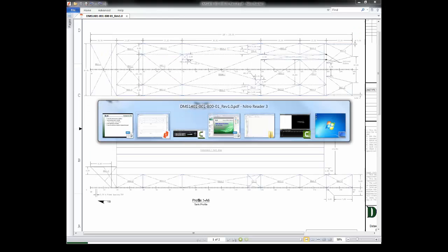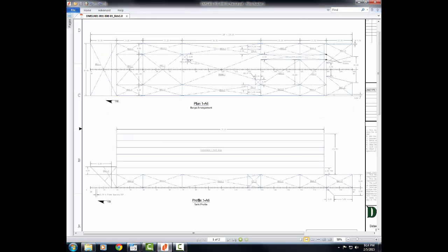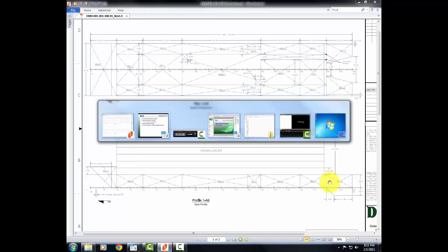displacement part. So if I can go back to the drawing here, notice we have a notch here in the aft end of the hull. This is an ATB barge, and so this is where the tug would come in. So I don't want you to model it with a section. I want you to model it with this whole part of the hull as one thing, and then add in the notch as a second displacer part that has a negative displacement.